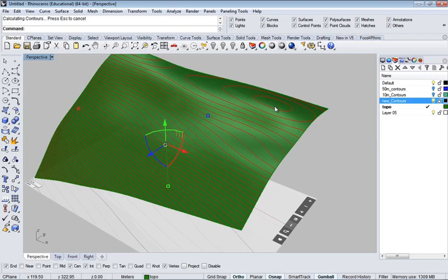A couple of tricks that you can do. A typical model would be laser cutting every single layer, which takes a lot, and you would stack the layers. But there are other techniques that save a little material. You could sort these so every fourth or fifth contour layer is what you actually cut out. You'd have one set that is 1, 4, 8, and then another that would be 2, 5. You see what I'm saying? When you lay those out on your page and cut them out, you don't have a complete overlap, and you get this stair-step effect.